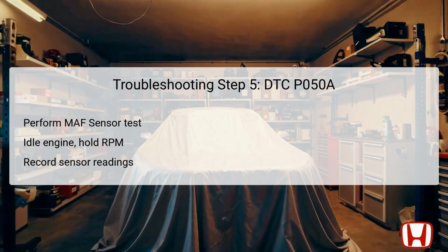Begin this process by starting the engine and allowing it to idle, while ensuring that specific conditions are met, including maintaining an engine coolant temperature (ECT) sensor 1 above 158 degrees Fahrenheit, 70 degrees Celsius, and having the vehicle in either park or neutral (N) gear.